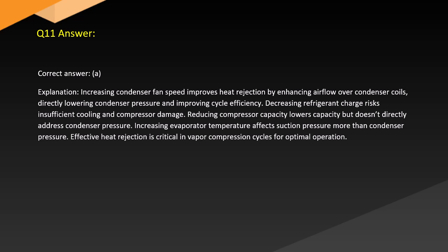Decreasing refrigerant charge risks insufficient cooling and compressor damage. Reducing compressor capacity lowers capacity but doesn't directly address condenser pressure. Increasing evaporator temperature affects suction pressure more than condenser pressure. Effective heat rejection is critical in vapor compression cycles for optimal operation.